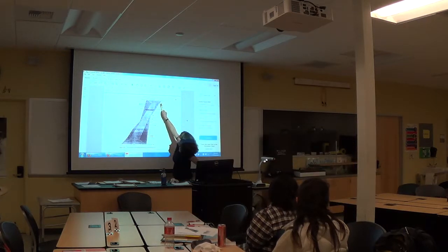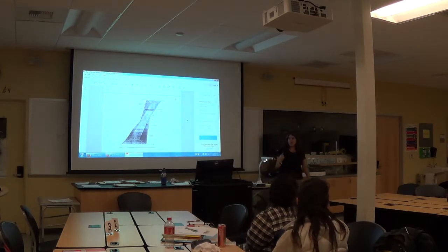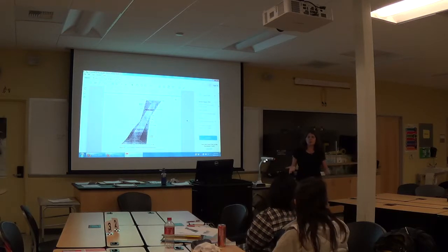When I dig out that soil and I put it on a pile on the side, on the site, is that pile going to have the same volume as the volume that I cut here? It's the same exact soil, but it's not the same volume. Why is it not the same volume? More aerated. It has more air in it. It's more aerated.